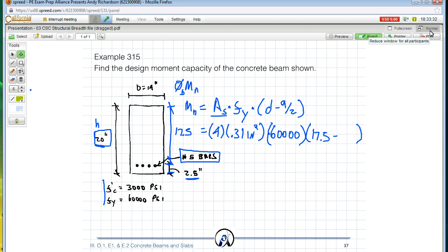The A is basically the amount of concrete. There's kind of an imaginary value here, and that's the amount of concrete that is effectively being used in the compressive portion of this, and it's set equal to the tension. And so we kind of need that value A in order to compute this. And people a whole lot smarter than I have determined and kind of set this information equal.